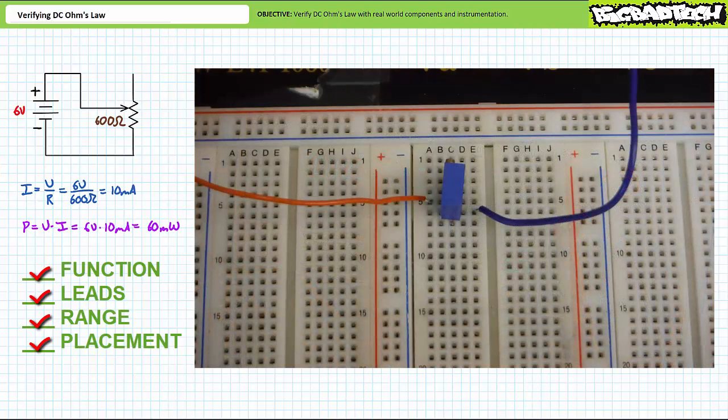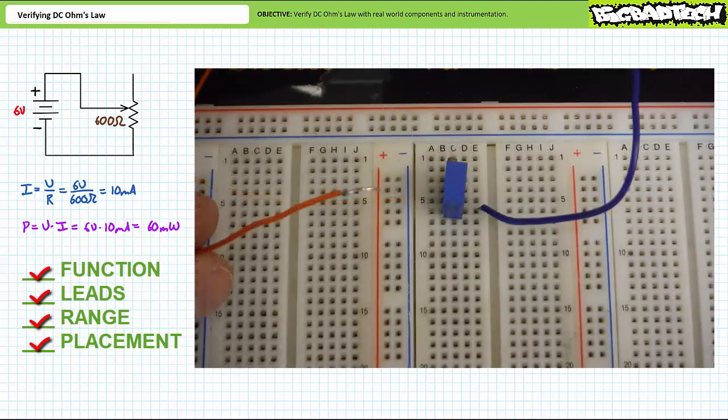Inside the low current input, this particular DMM is auto-ranging. Placement. Ammeters measure current through a circuit and are placed in series, or in line, with an element of interest. Consider the original unmodified circuit, where the adjustable middle terminal of the potentiometer and positive terminal of the source landed at node 5A through E, and the bottom terminal of the potentiometer and negative terminal of the source landed at node 6A through E. We need to break this circuit and insert the ammeter such that all current passes through the ammeter. Break the circuit so that the source positive terminal is no longer landed at node 5A through E, but rather dangling out in space. This is an open circuit and no path exists through the potentiometer.